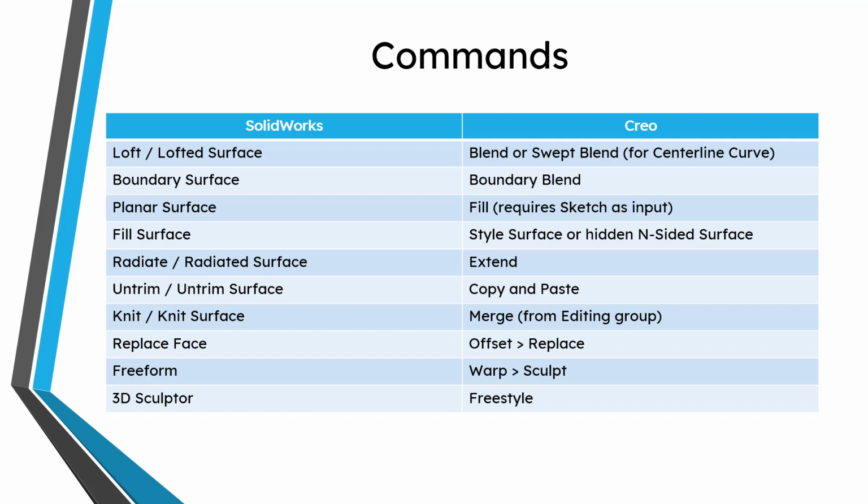To replace a face in SolidWorks, that's from the offset command with the replace option in Creo. You have the freeform command in SolidWorks. In Creo Parametric, that's through the sculpt option in the warp command.